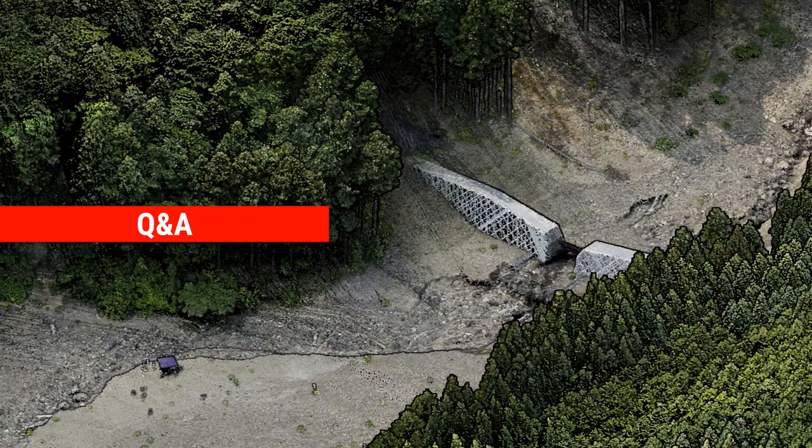All right, here's another question we have from the chat section. Can you now apply the geoids to the trajectory and export from SE? I think there is a way to apply a geoid to a trajectory. That isn't usually what we want to do, because the longer range scanners you have, we really want to apply the geoid to the points, right?